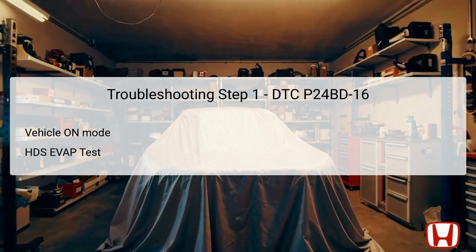The first troubleshooting step requires the technician to turn the vehicle to the on mode without starting the engine. This step allows the vehicle's onboard diagnostic systems to power up and communicate effectively with the Honda Diagnostic System, HDS. Next, perform the EVAP leak check module test using the HDS. This test checks for abnormalities in the EVAP system, specifically the leak check module's functionality.